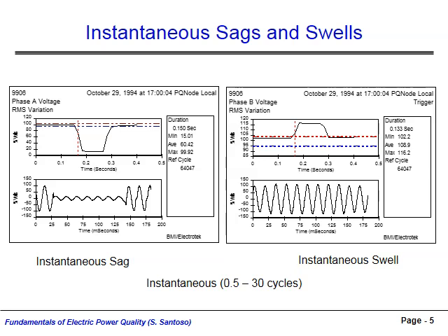This phenomenon can occur in a system when the zero sequence impedance from the perspective of the fault point is higher than the positive sequence impedance. Because the duration of this disturbance was less than 30 cycles, the sag and swell are classified as instantaneous.